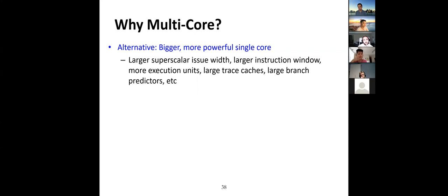I guess there's a lot more possible ways of ordering different instructions, and that can get really annoying. Dependencies, right? Unfortunately, the dependencies don't scale linearly, they scale quadratically with the size of the instruction window. And that's the biggest bottleneck. The things you mentioned, guys, are also problems, but before that, the first thing you face is that. So Behrus said there are more data dependencies. That's correct. So data dependency is the problem.